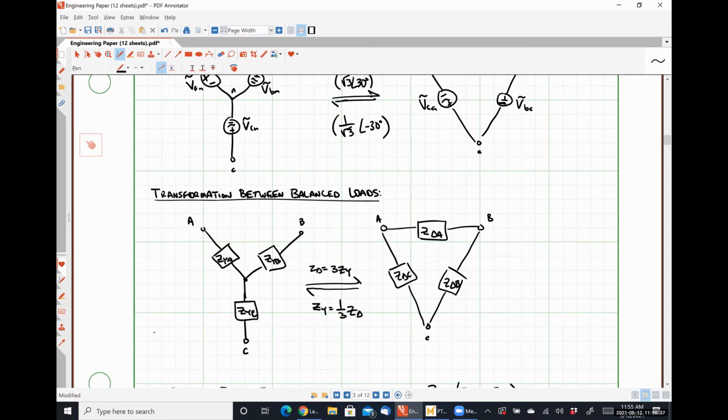And also we're going to run into three-phase in industry, absolutely. If you go into power, you're going to be dealing with three-phase power systems the overwhelming majority of the time. Even if you go into solar, which creates DC power, if you want that DC power to do anything, like power a house, you have to run it through an inverter. The inverter is just a series of switches that makes that DC signal look like a three-phase voltage source. So it's all, you know, well, I take that back.